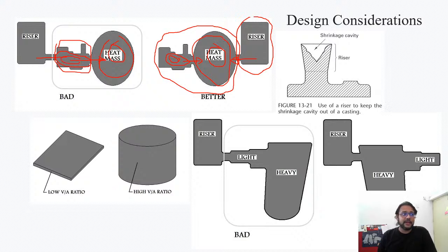So what will happen is that at this junction, there are chances that a small cavity is created which is entirely vacuum. It's not able to pull in material because the material is not molten, the riser is over there, and this is shrinking. Because of that you would have a small area here where there will be a cavity, and this is a shrinkage cavity. The same concept is shown in these images also, this one and this one.